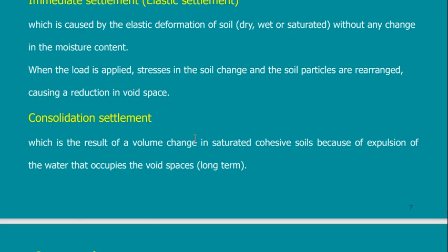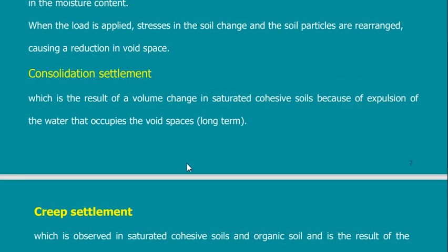It needs an enormous amount of force. You cannot compress water. But if you have air, you can compress air. If you have a bowl that is full of water, try to compress it, it will not be compressed. But if it is full of air, it will be compressed. So consolidation settlement is a volume change due to the change of the amount of water inside the voids, but this will take a long time to happen.